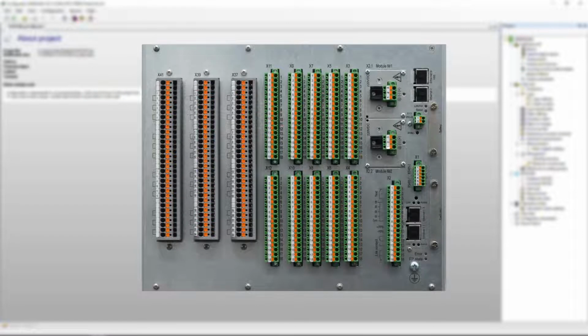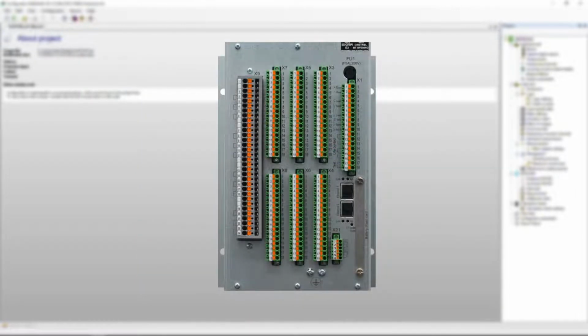PTP synchronization is available in all IEDs, except the 1/3 of 19-inch size, with Ethernet 1 interface on the back of the IED represented by 2 ports. IRIG-B synchronization is supported in all IEDs, provided there is an additional sync connector. In IEDs with a 1/3 of 19-inch size, IRIG-B is always supported, and the sync pulse is supplied to terminals X19 and X110. Up-to-date information on the connection to the connectors is given in the schematic diagrams and on the marking of the back plate.